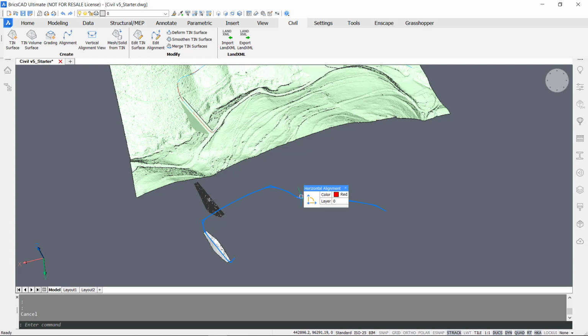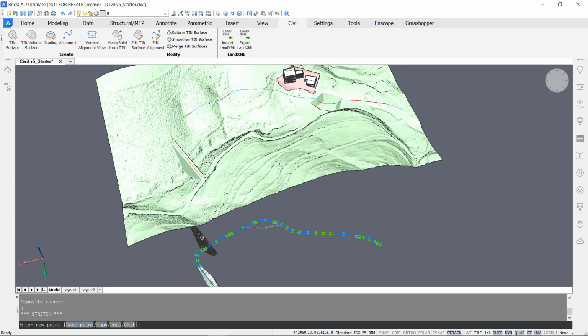there is a horizontal alignment projected on level 0 of the Z axis. And these are actually connected with the 3D model. So if I change anything here, it will be reflected directly onto the 3D alignment here, you see? Let's press escape back like this.